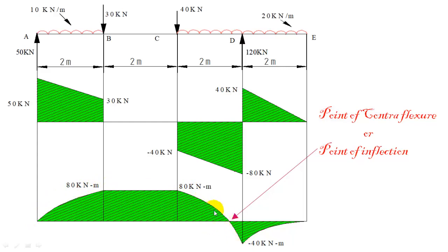So that will be the nature of variation. It will not vary like this. You should not draw it like this. Again, you should not draw it like this. For the bending moment curve I am talking. You should always draw the bending moment curve with the concave side down. And this is how the parabolic variation for bending moment changes.